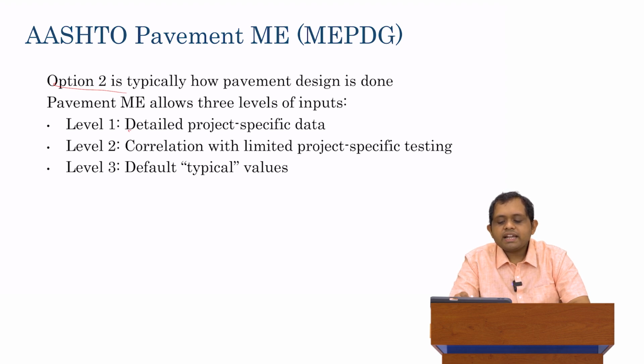Level 1 is where you collect detailed project specific data. So you might do all your geotechnical work, you might do all your mix design, you might do your traffic modeling, etc. right in the beginning before doing any pavement design.